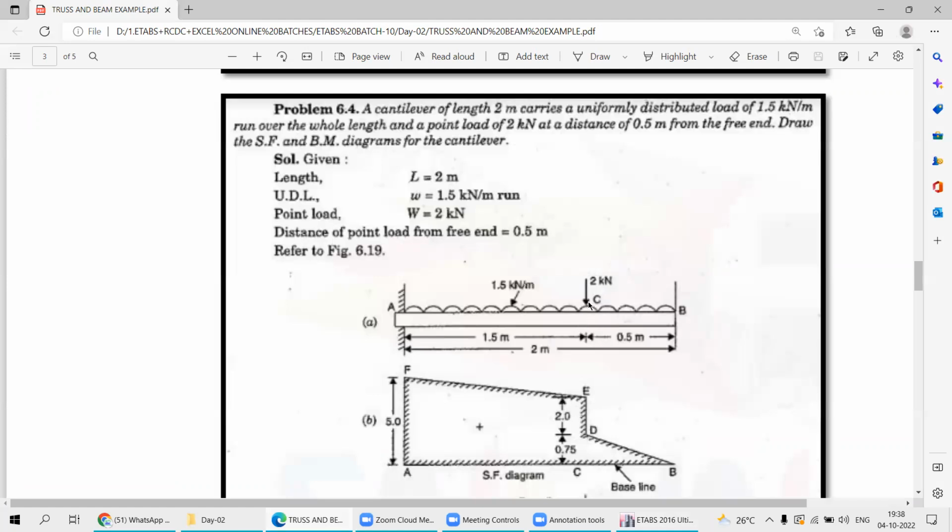And this point load you have to apply over the frame, over the beam. So tell me, is it needed to break the beam here, or can I take the continuous beam? No need to break the beam. Exactly, very good. In the last session, we have covered this point. So it is not needed to break it. We can take a single element, it is a single beam. So why would you break it?